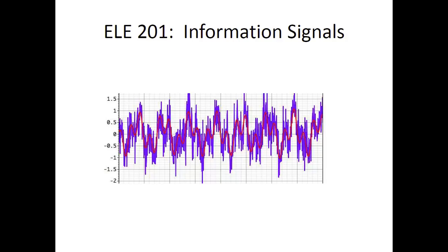Now, you actually can get different effects depending on how you do the averaging. For example, for each output point, you could just go a certain number of samples or a certain length of time before that point and after that point and just take an average of your signal. That average then would be your output at that point in time, or that time index. That's one way to do it. But you could also do a weighted average. You could count the points closer in time more heavily and the points further away in time less heavily.